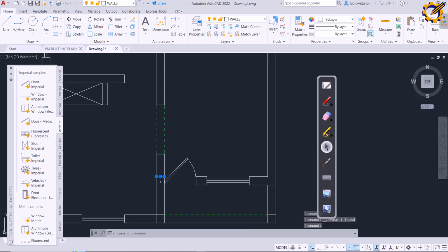The reason why I didn't remove this line is to show me where this wall ends here. Because it is at the end of this wall here, I'm going to fix that door. That's why I didn't remove it. Now since I fixed the door, I can now remove that line. So if I want to open it 90 degrees, no problem. Just come here and open 90. Here you get.